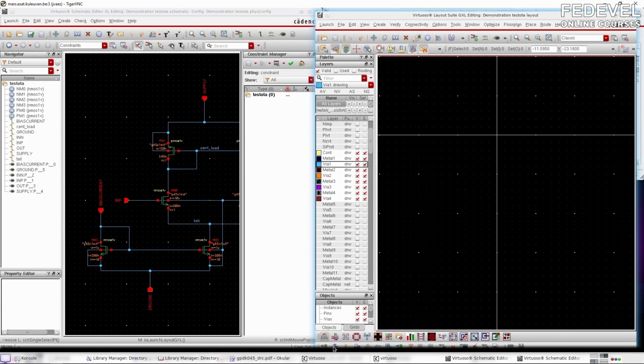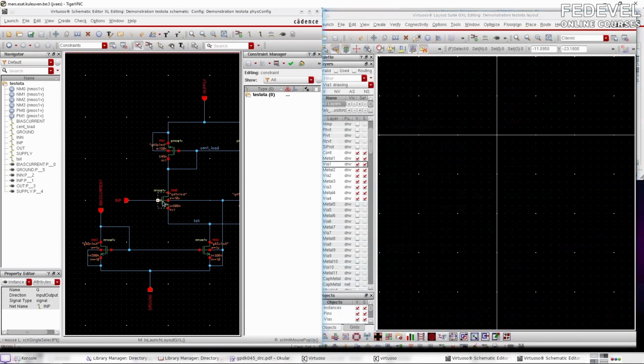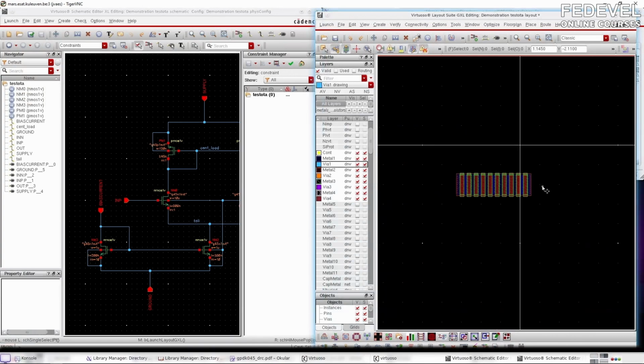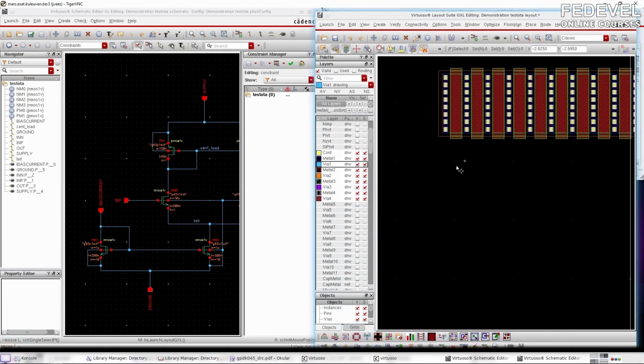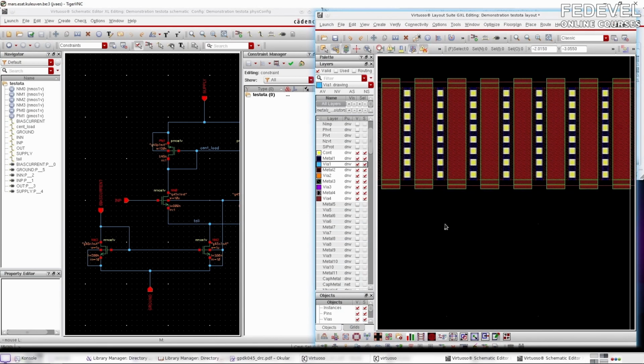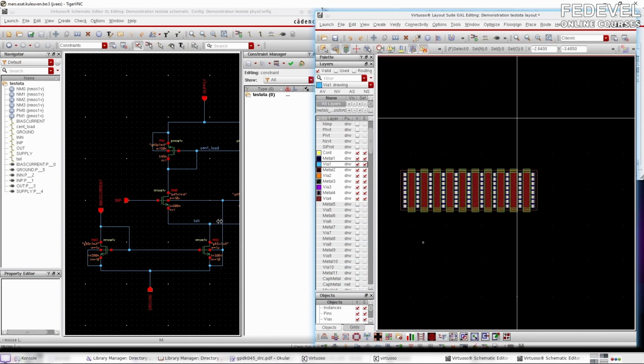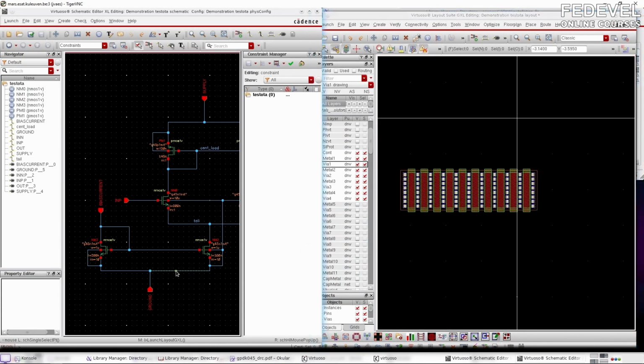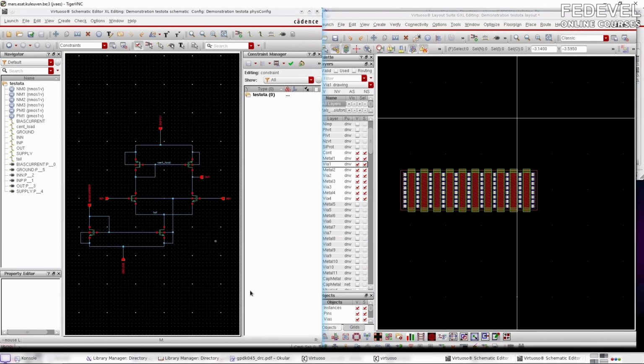Whereas here, if I now place a transistor, this is really a top-down view of a transistor, with in red the gates, and these are the sources and these are the drains. So these are the recognizable terminals. And then I can even do interesting things with what we call interdigitizing, but I'll show that maybe later. Keep it simple for now.